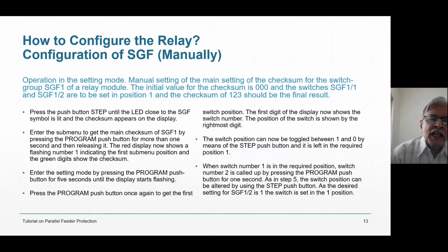How to configure the relay SGF. SGF, how will you configure? SGF is a group which decides the characteristic: definite time, normal inverse, very inverse, extremely inverse, long time inverse, which kind of characteristic. And that kind of characteristic you can set manually.